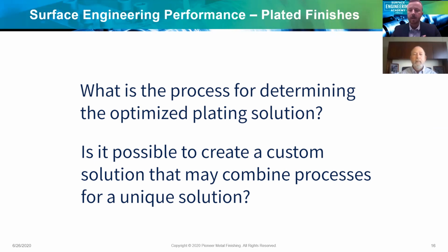But if you look at the old plating technology, and I say old, I mean the traditional plating technology that pervades much of manufacturing today, typically hardness and corrosion resistance operate in conflict with each other. Typically to drive corrosion resistance, you're adding co-deposited phosphorus with nickel, nickel phosphorus, Electroless Nickel. Well, the phosphorus is great for corrosion resistance, but it softens the coating and so has an impact on wear. So all things to consider, but to Steve's point, yes, some new technology is being developed now, and certainly opportunities to partner and to work with opportunities in the marketplace.